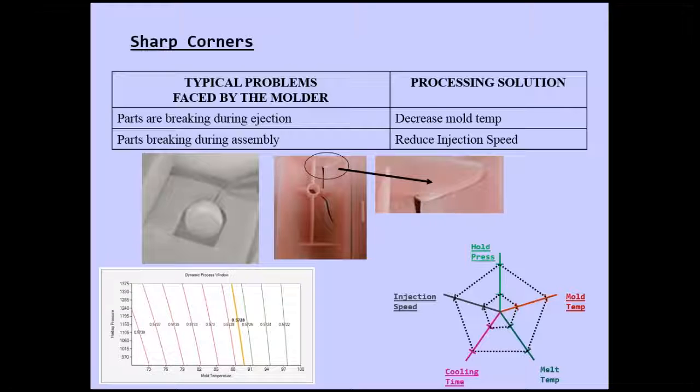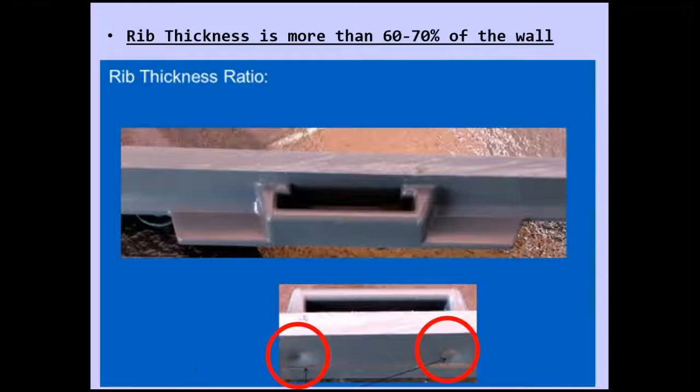So mold design and part design are related. There's a huge relationship between them. You can have a thin part, but then you need to have very good venting in the mold in that area also. Any thin part has to have good venting. So looking at these things, sharp corners is one of the major things that I see, especially if you can't take the parts out, including draft. Sink, yes, I see this quite a bit.